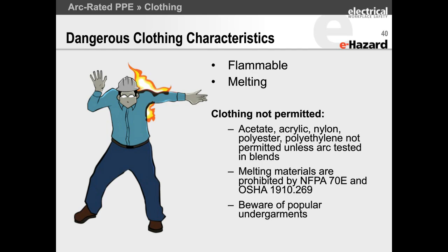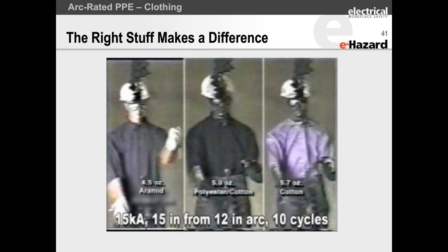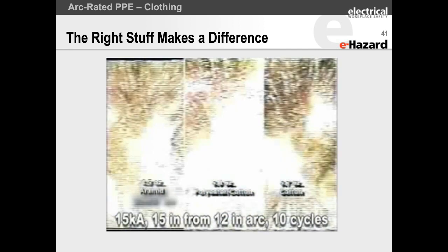So we want to make sure, even if we're de-energizing all the time, that we have the proper PPE in place. We want to make sure clothing is not ignitable. Now, that's a little bit of a problem in the new standard since it eliminated that below 1.2. Realize that still by law and also by 70E, you can't wear ignitable clothing at any risk of arc flash. So that could ignite clothing.